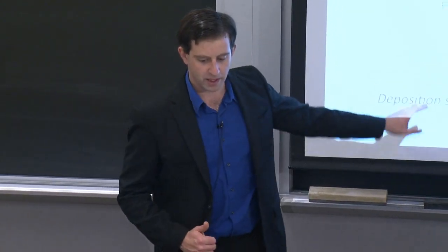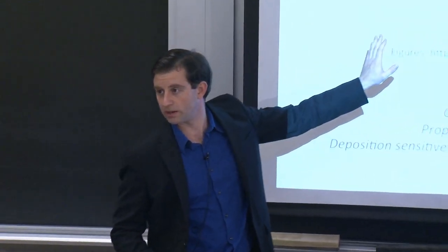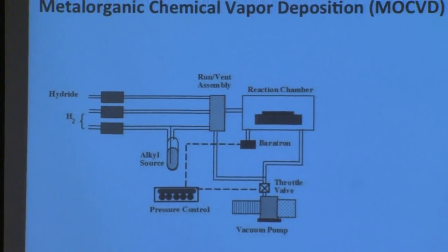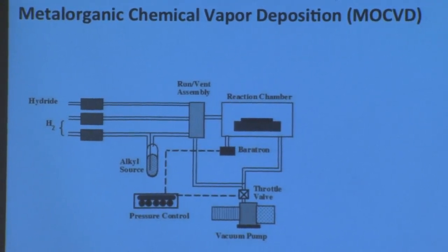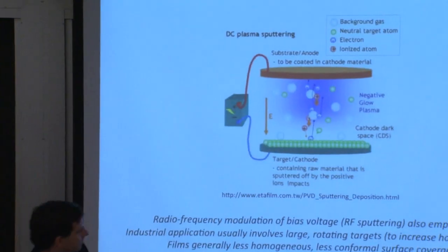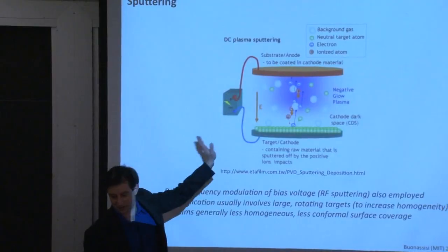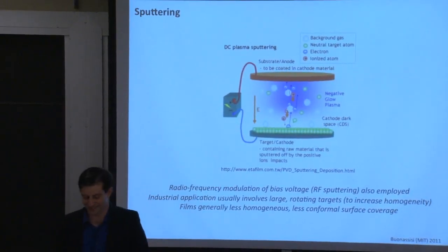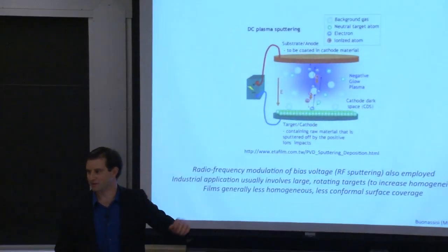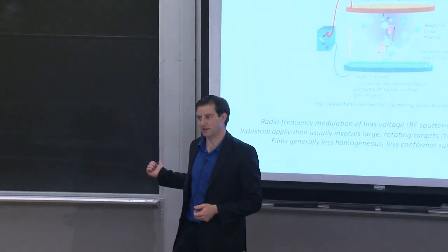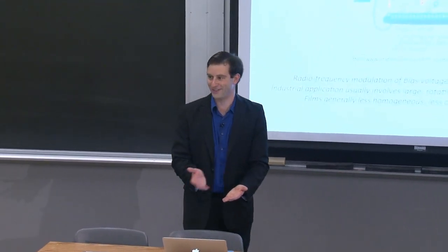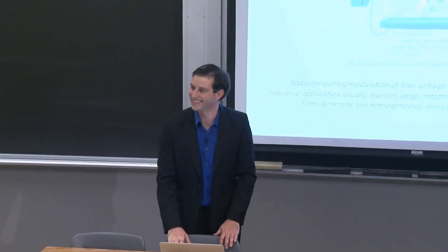So from an MOCVD point of view, you could do a distillation process and increase the purity of your precursor gas and avoid that. So I think there are two big reasons why MOCVD can produce higher purity films than a sputtered system. One is the quality of the target. And the other, I think the bigger parameter, at least in our growth systems, is cross-contamination. Whenever you deposit, say at EML, they have a sputtering system there from AJA, or over at Harvard CNS, there's another AJA sputtering system there, you're going to get cross-contamination. Just look through the logbook and see what people have tried to deposit. It gets kind of scary.